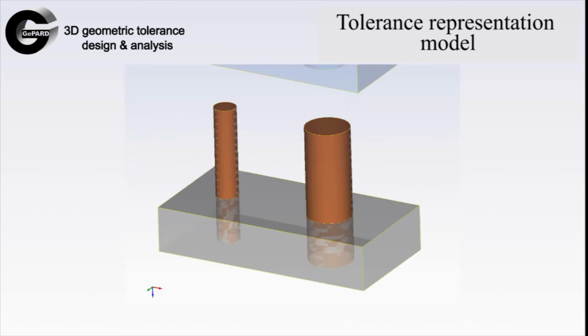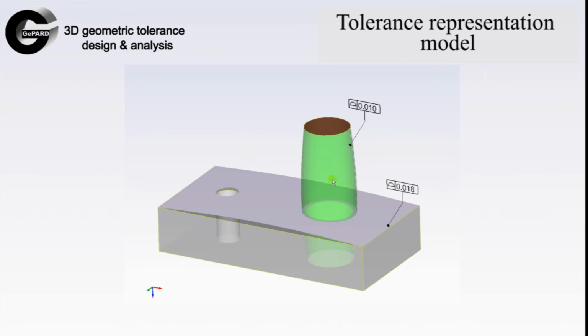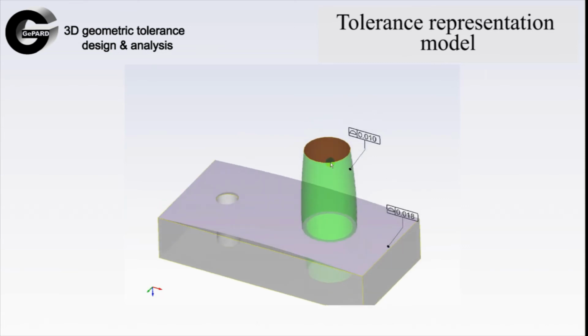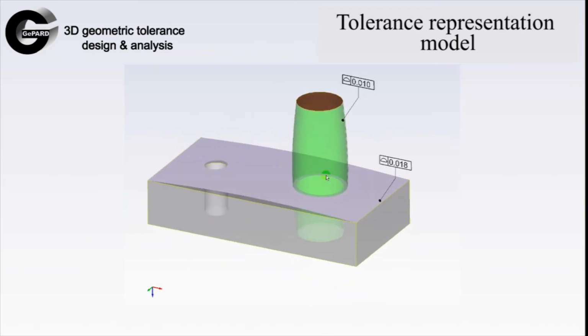Examples of form tolerances are special cases of deviation from flatness tolerance, the convexity and concavity, and the deviation of the profile of longitudinal section of a cylindrical surface, namely its special cases, barrel shape, saddle shape, and so on. In this case, with some assigned tolerances in mind, some allowable surface locations are represented in terms of variations of coefficients of the first and second fundamental forms.